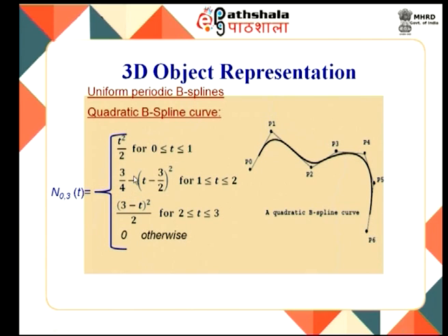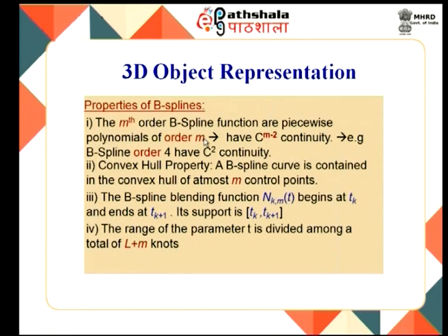So, you do not have to do a derivation further. If we see the properties of B-splines, as we had seen the properties of Bezier curves, similarly we have got properties of B-splines. They are also well behaved, the blending functions that define the B-splines sum up to unity for every t, and they are more generic in nature. That means the knot vector, even if it is a uniform knot vector that we have considered, we can derive Beziers from B-splines. So, they are more generic, as we will see further in the properties.